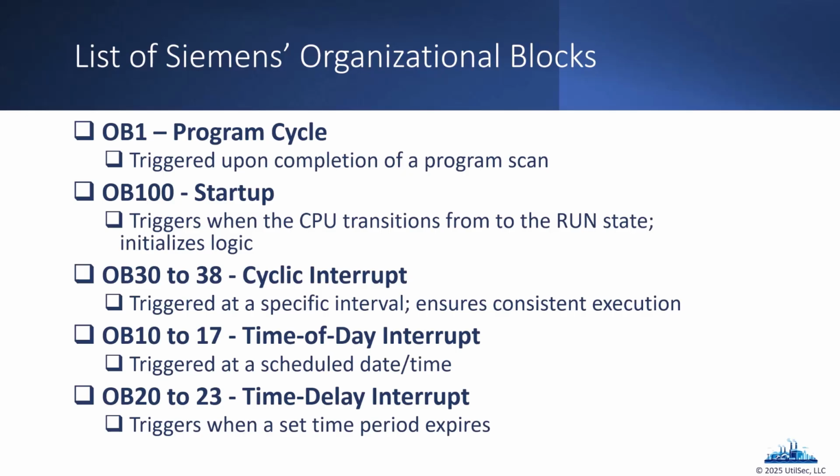What happens when we bring a PLC online? It moves into run state. At that point, it's like booting Windows, and now Windows is starting to load. Then you have to start to initialize the logic of the PLC for it to actually do what it does. And then you can see a few more, again, time of day, cyclic interrupt, where it's at a specific interval.